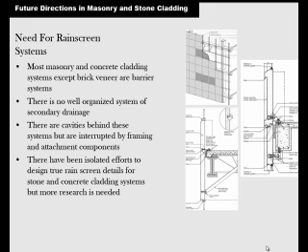So you need to make sure that you think about how it's going to drain if the water gets in there, because it will get in there. There's just not a 100% way of keeping it out. The cavities behind these systems, when they get interrupted by the framing and attachment components, that's where you've got to worry about it. So you need to provide some sort of drainage mechanism when you do that.